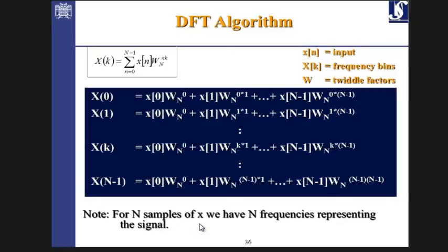So we know about the down and up sampling, what it theoretically means, but about the application, when we go to the filter bank, design of the filter bank, and polyphase filters, then we will explain how the polyphase filters are implemented using the up and down sampling, and computationally much more efficient than the standard version of that.